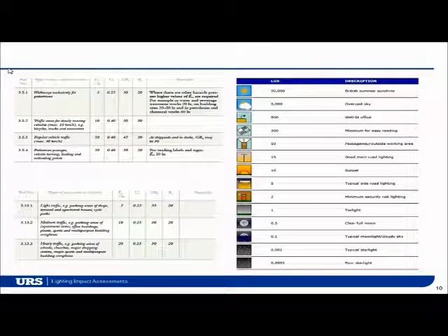This is just an example of some of the light levels that we're talking about, ranging from 5 lux average illuminance on a pedestrian path up to 10 to 20 lux in medium traffic, heavy traffic areas and car parks, and also some of the levels that we come across in the natural environment. These levels from the code should always be used as maximum levels so that we're not overlighting areas.